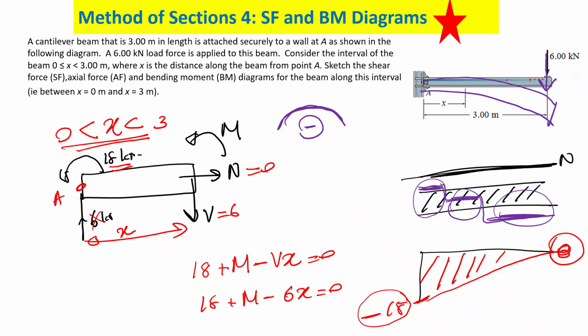This is hogging. Hogging means in a concrete beam you have to put the steel reinforcement at the top. Why? Concrete can only take compression. The top of the beam is in tension, isn't it? When it goes like this, top is in tension, bottom is in compression. So you need to put the reinforcement at the top. If you don't do this, you will put the reinforcement in the wrong place. Then the beam can't survive, isn't it?